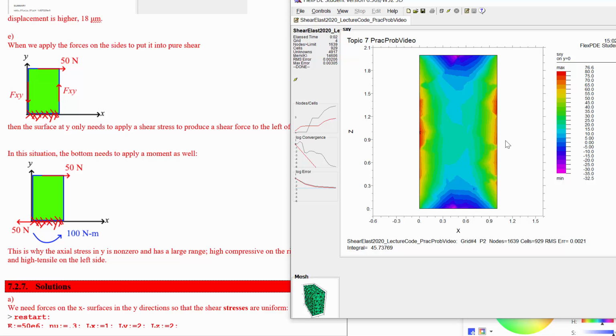This is the set of extra stress on Y equals 0, which means that we're pulling it more to the left from the wall. The wall is trying to pull it this way, stopping it from buckling in the other direction. And the bottom and top are being pushed more to the right. So with the negative stress there, the wall is pushing it to the right at the top and bottom and pulling it to the left in the middle.